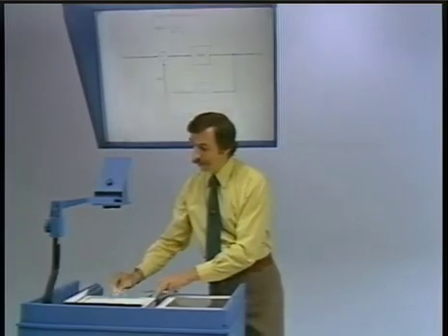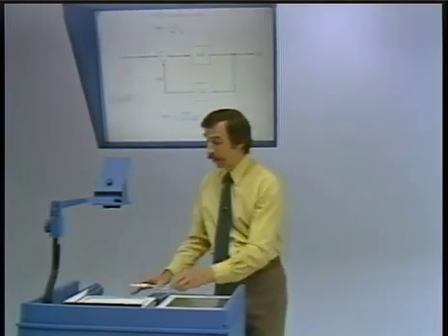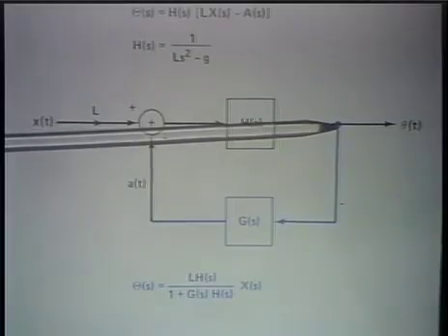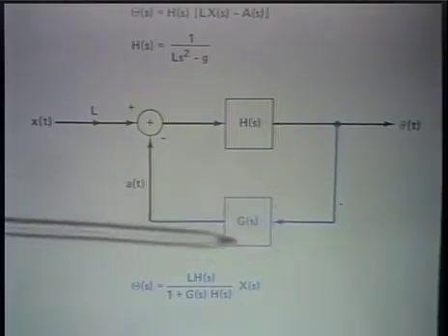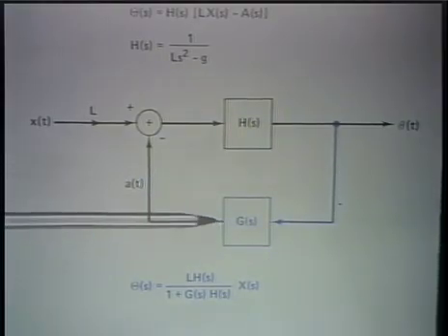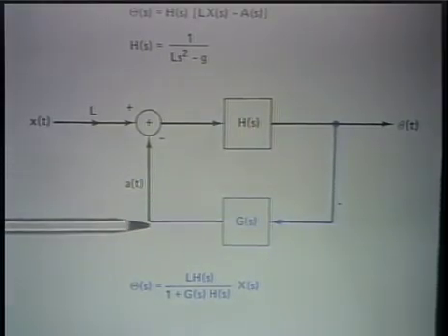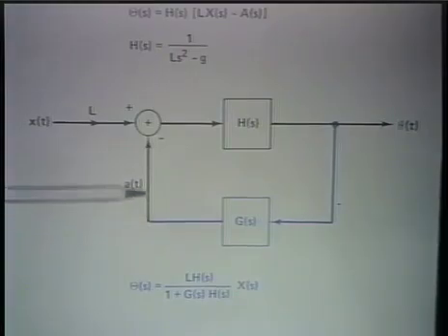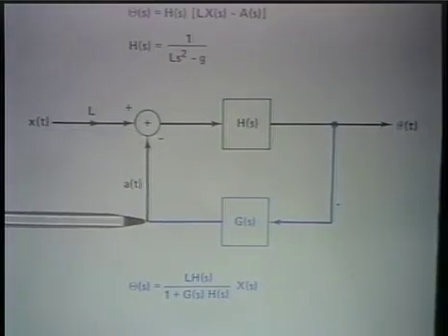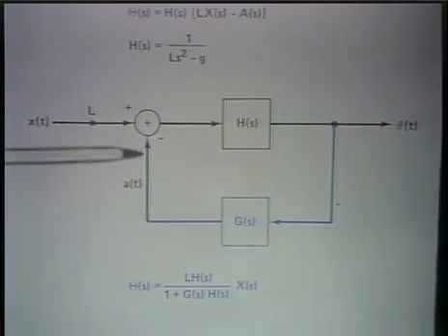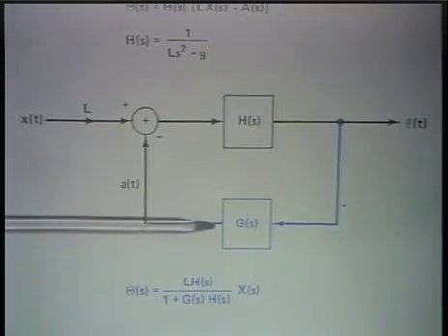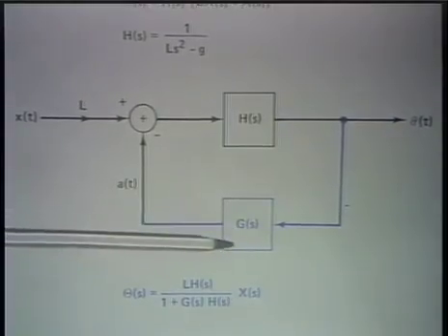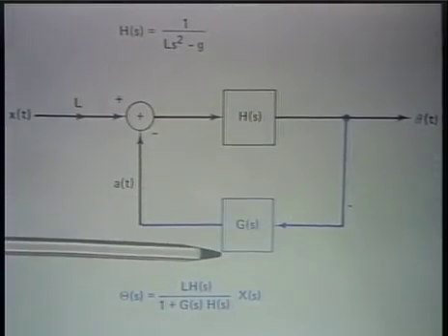So with feedback applied around the system, there would be some measurement of the angle through some appropriately chosen feedback dynamics, and that would then determine the applied external acceleration, corresponding to what the motor does by pulling the cable back and forth. And we would like to choose g of s so that the overall system is stable.